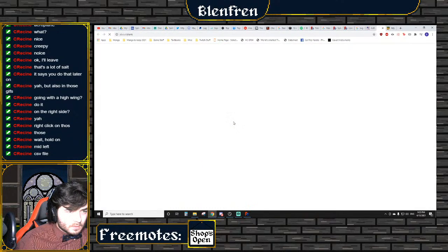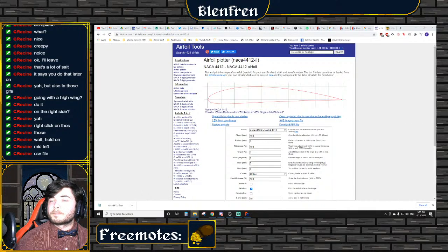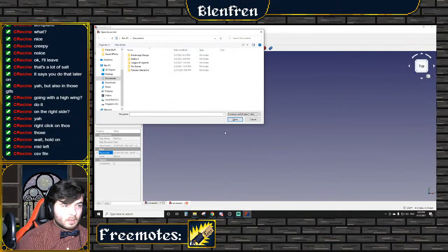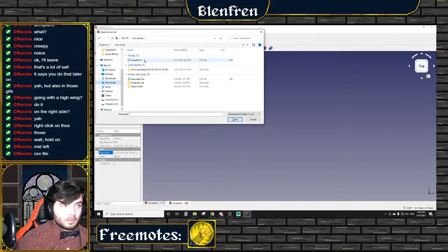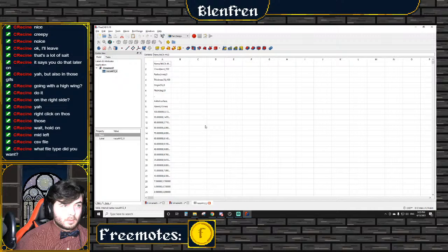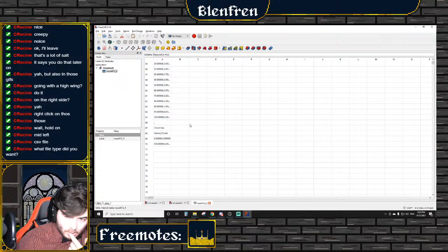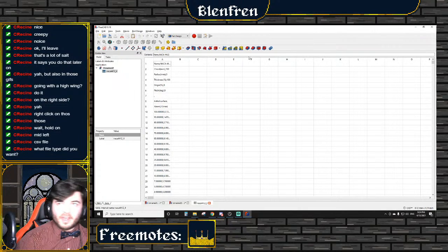CSV file of coordinates? Okay, but that's a CSV file. I suppose if I do that, right? I can actually just go into here, and instead of doing common airfoil data, I can do CSV format. And then, what file type do I want? I want a DAT file.